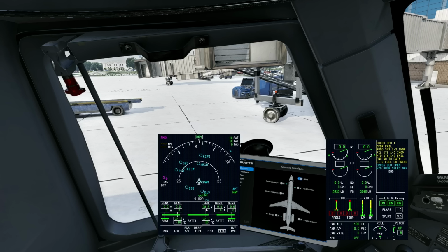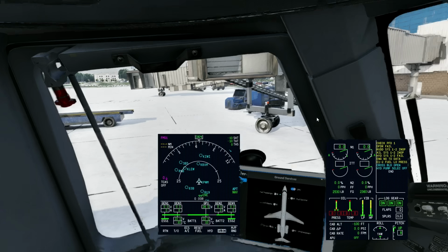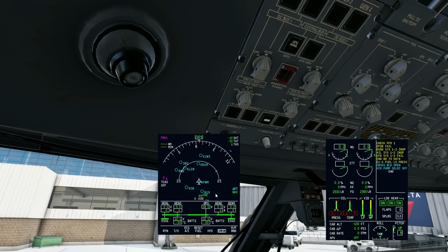It's connected, and we're showing 28.5 volts. 28.5 volts is an acceptable amount of GPU output. If it's putting out more than 29 or less than 26, don't take that GPU. So we always check this. In the sim, obviously, it's going to put out 28.5, but you'd be surprised what you see on the line. So I'll go ahead. I like this. I'll take it. We select it.